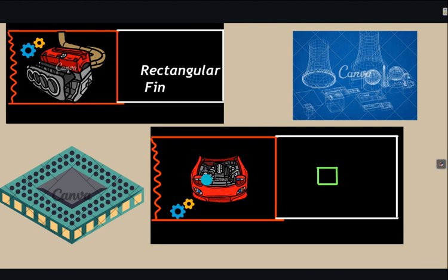Okay, fine. So the way you derive the governing differential equation is you first consider a small calculus element. The one that you see in green, that's the small calculus element. Maybe before you do that, you have to set up a set of coordinate axes. This is going to be your x-axis, this is going to be your y-axis, and the small calculus element, this green square that you see, is considered at a distance of x from the left extreme end, and at a distance of y from the origin of the coordinate system. So that's a small calculus element.